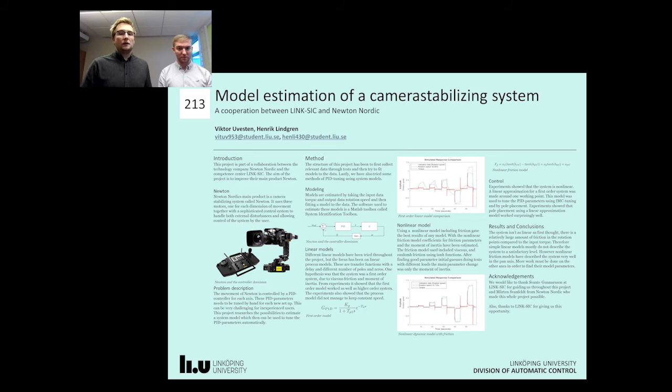From the model estimation of the first order systems, it showed that the systems only worked around the given working point. When we changed working point, the model failed to simulate the true system. This indicated a non-linearity in the system. This non-linearity, after a lot of investigation, seemed to be dominated by friction. When we used a non-linear friction model with our first order model, the result was promising.